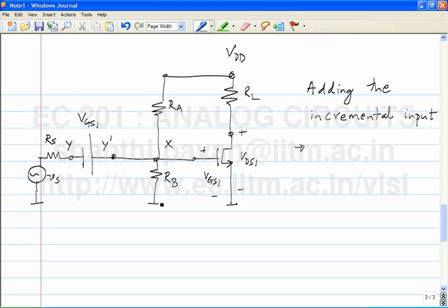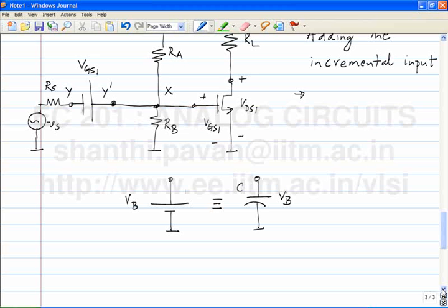The potential between the two nodes must be the same regardless of the amount of current being drawn from the source. One observation is to note that a battery of value VB is completely indistinguishable from a capacitor charged to value VB, provided what? A battery of voltage VB is absolutely indistinguishable from a capacitor charged to the same voltage, provided no current is drawn from the capacitor.